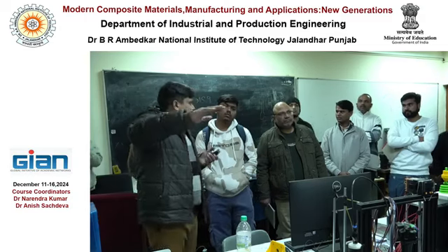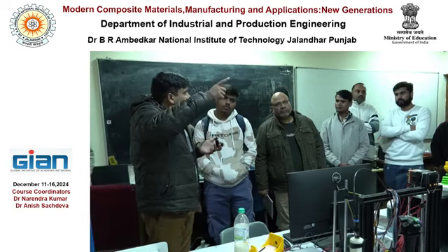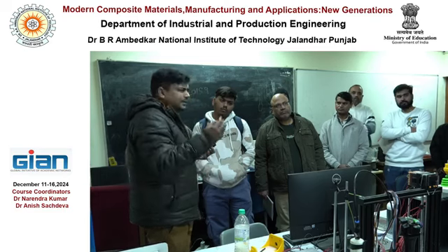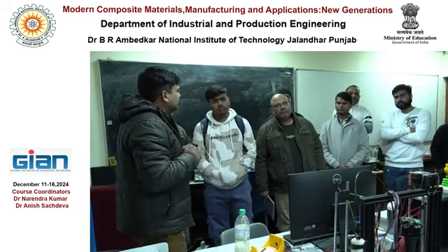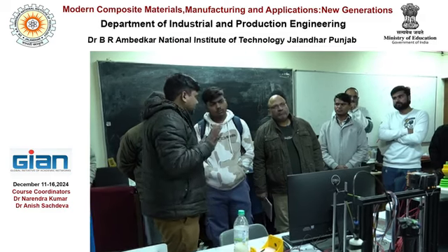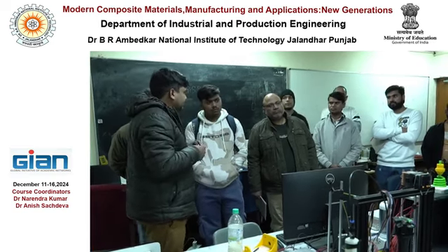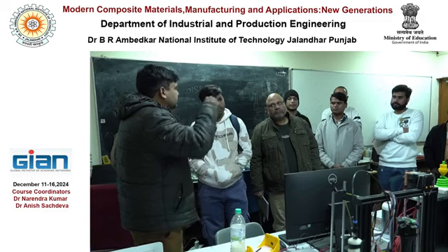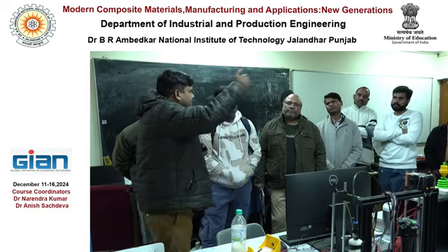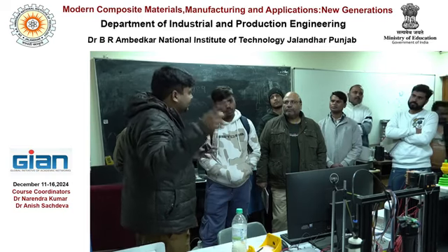Earlier, the whole part was oriented in the X and Y direction. So at that time, the height of the specimen was only the thickness of the specimen, let's say 6 mm. And suppose I have opted for a 0.4 mm slice layer thickness. So how many layers do I need to add to complete the fabrication of the sample? 0.4, 0.4, 0.4, so 1.2. Again 3 more layers, 2.4. Again 3 layers, 3.6. The specimen thickness is 6 mm.